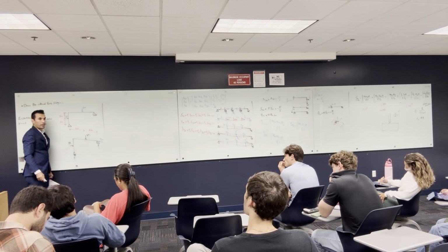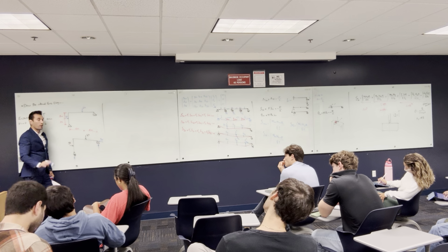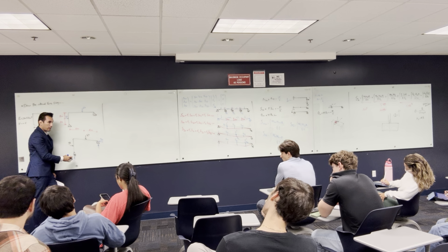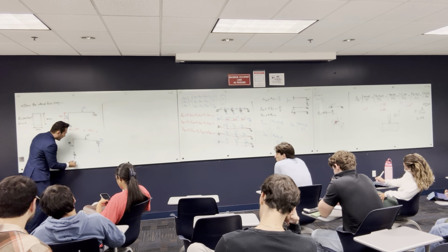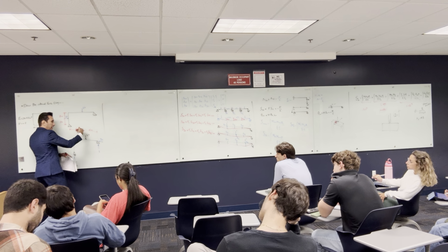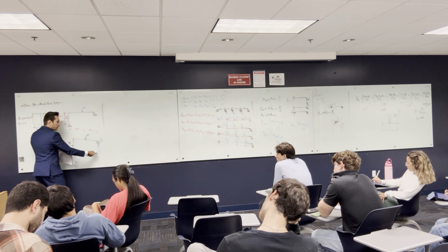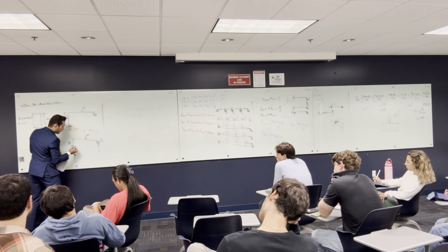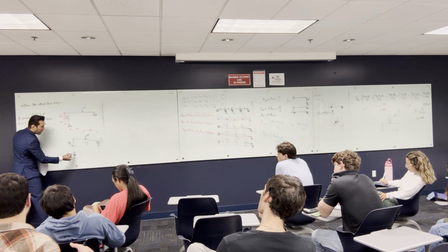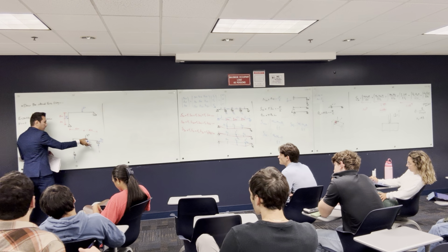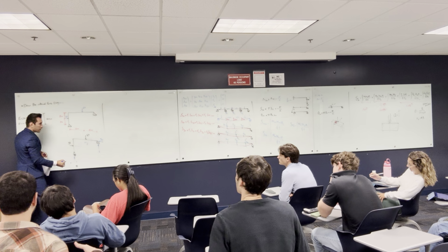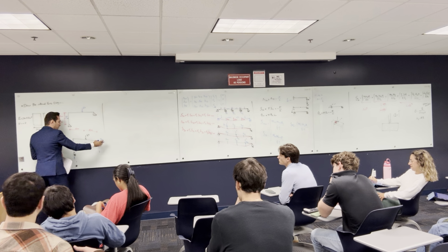Can we solve it without doing the equilibrium? Okay, let's see if it works. This 6 is going to be divided into 3 and 3, so you have 3 here and 3 here. But this 3 with the 3 is going to make a couple, a moment that way. It's going to make more compression on this hinge. So I would expect this to be plus, and you need a moment that counters this moment.